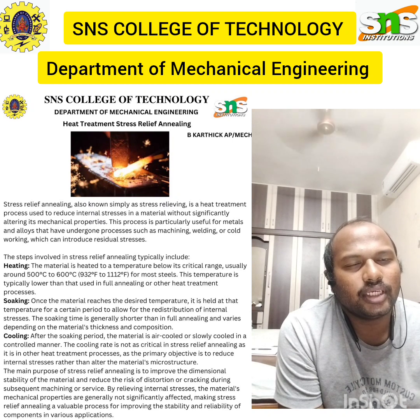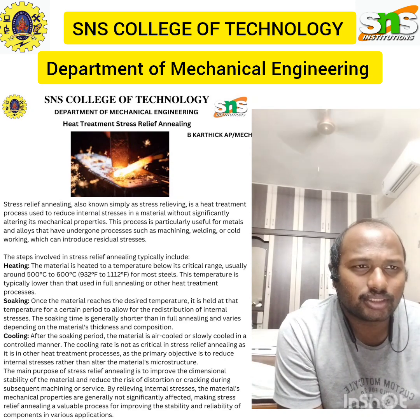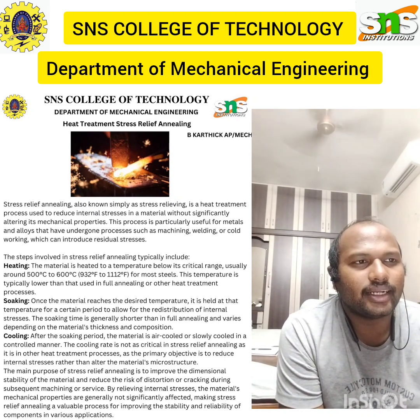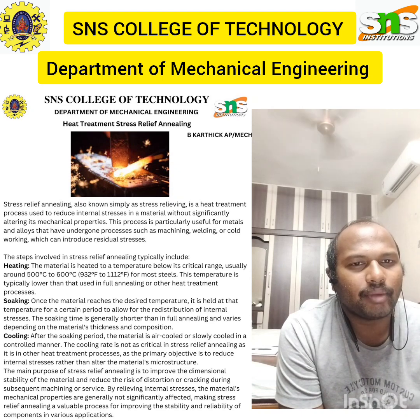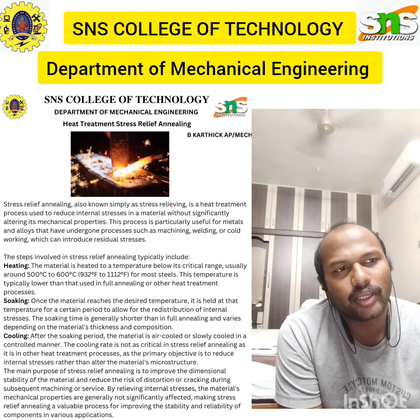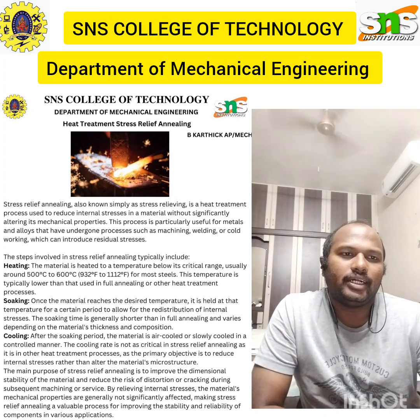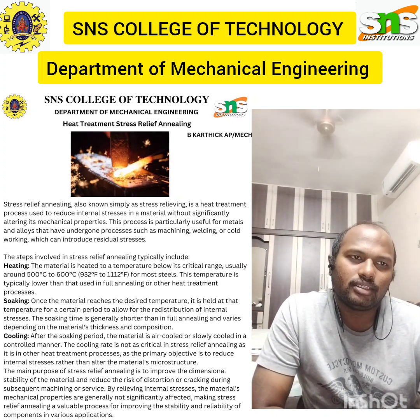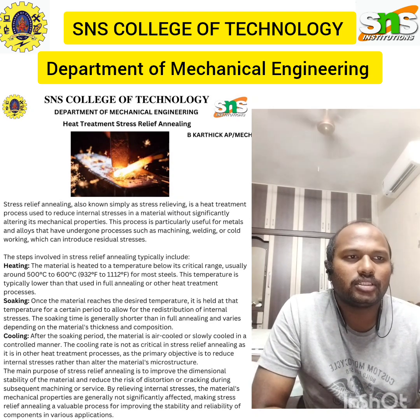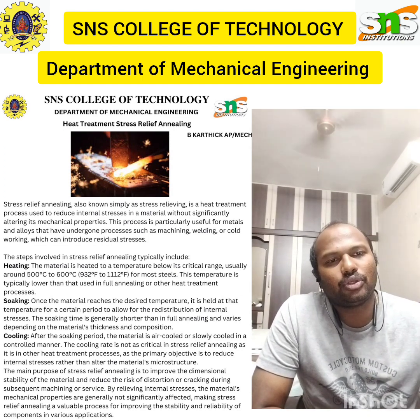Okay. So here stress relieving annealing is a heat treatment process used to reduce the internal stress within the material, typically metals. These internal stresses can arise from various mechanical processes such as casting, welding, machining, or cold working. So stress relief annealing helps to improve the dimensional stability of a material, particularly metal, and reduce the risk of distortion or cracking during subsequent processing or use.